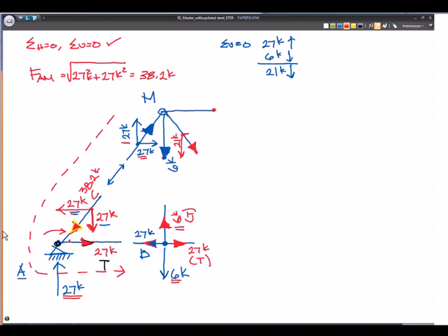Okay, so the very first thing that we did was if we had 27 kips up, that was our reaction, we needed 27 kips down. And that's what tells us that it's facing down right there. The verticals are in equilibrium, so this resultant has to be pushing down. Okay, so it looks like you got it. Okay, great.